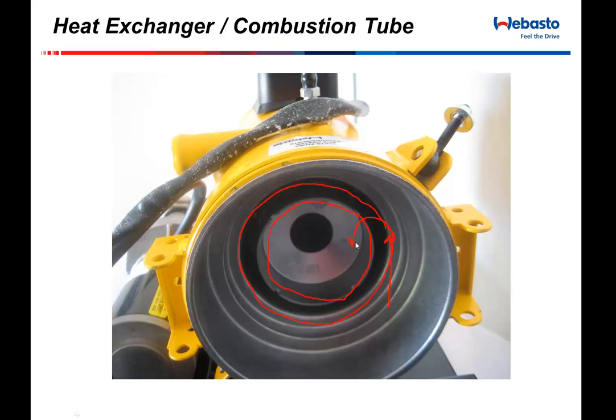And the result is that the photocell, even though it's working and the photocell is good, can't see through all of that heavy carbon, so it never changes resistance and never allows that heater to operate. So again, that disc is making a nice seal around this area with the nozzle going right through the middle.